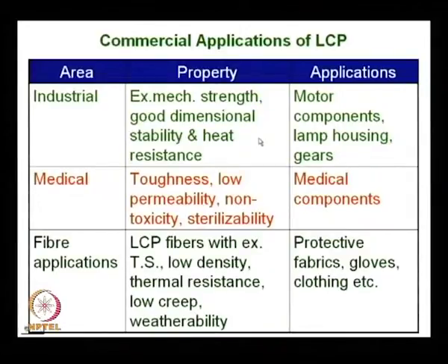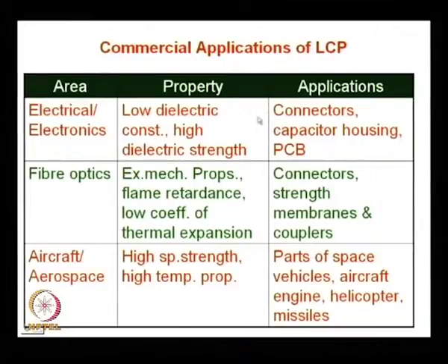So, even for biomedical applications, these liquid crystalline polymers today make a major contribution, and industrial motor components, lamp housings, and you see some muscle actuators also, artificial muscle actuators are made from these liquid crystalline polymers. Okay. Electrical applications: connectors, capacitor bushing, printed circuit boards, for fiber optics, connectors, strength membranes and couplers, and aircraft, parts of space vehicles, aircraft engine, helicopter, missiles, and so on.